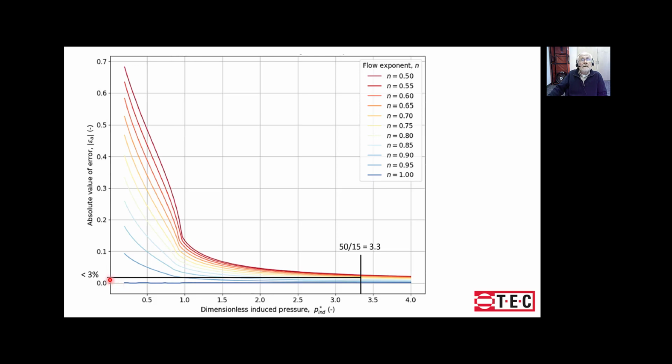So even though you may measure the baseline pressure at the bottom of this building, which could easily be 10 pascals, and according to the ISO 9972 standard, you can't do a valid test on that day because the stack effect is too high, this graph tells us the worst case error due to the stack effect is less than 3%. So why not? So we're hoping that this gets used by people writing standards and people developing.